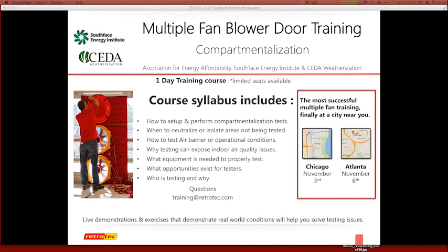The next point would be, there was a question that someone asked about stack effect and door openings and pressure balances when testing whole buildings. We have an Excel spreadsheet that does a very nice analysis. I created it originally when someone was doing a 30-story test and was concerned about stack. It will demonstrate, if you're testing to 50 pascal, that you can actually tolerate as much as 50 pascals of stack on the top of the building and still get decent results, provided you test in both directions. The spreadsheet will tell you exactly how a building will perform before you go out there to test.